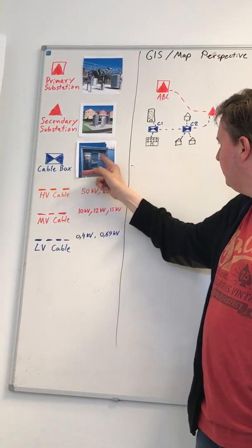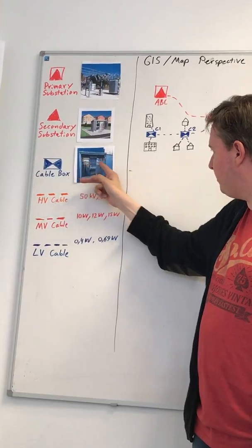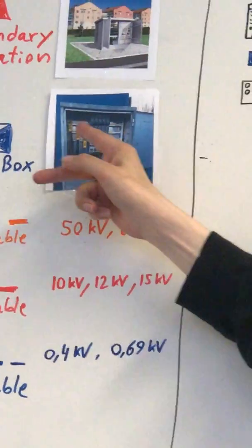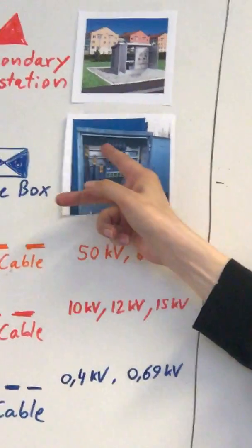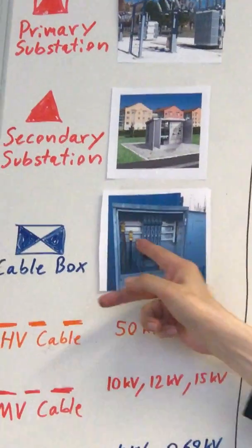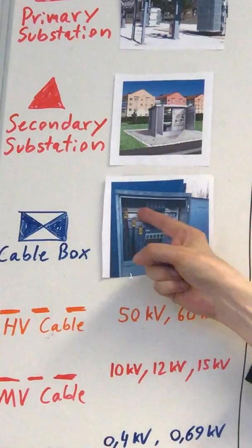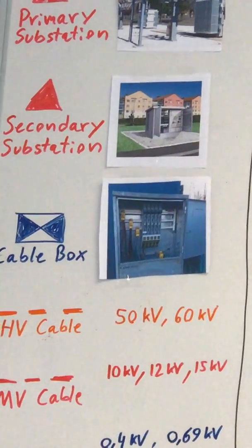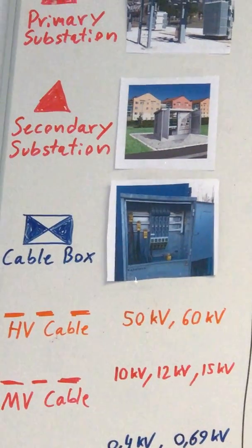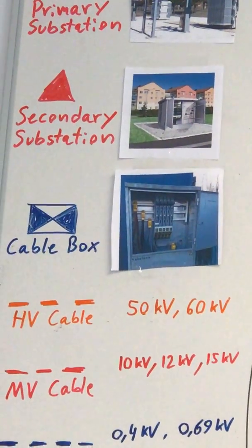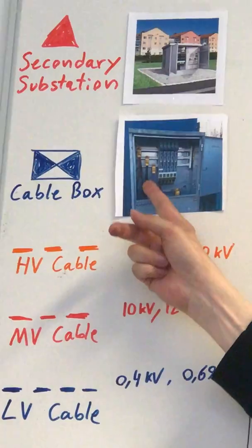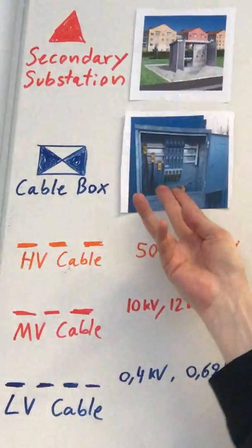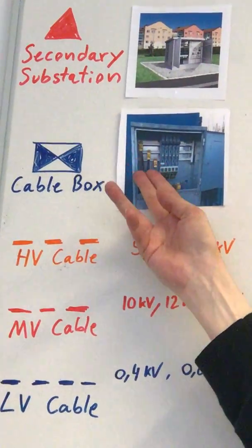These are the 3 things going in the back end. This is what we call the bus bar. Which one is the bus bar? The 3 pieces of copper or iron going here. So this is one per phase, right? Phase A, B, C, because in the electric world we always have 3 phases. You can see there's 3 cables going up here, but that's actually 1 cable with 3 phases that is connected to the bus bar.